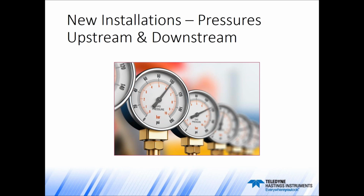On the flip side, if the downstream pressure or back pressure is too great, then the valve may give poor performance. One other note about this topic, some users will just buy a generic nitrogen flow controller, which can be fine. They'll use the GCFs, the gas conversion factors, to go from nitrogen to some other gas.